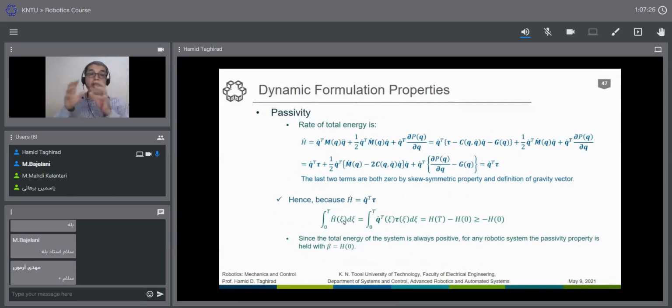If you have an interconnection of systems, suppose you have 3 different subsystems, and you have proven that all subsystems are stable, the Lyapunov approach doesn't mean that the whole system is stable; you should still find a new Lyapunov function for the whole system to find its stability. This is the limitation, or the difficulty, of using